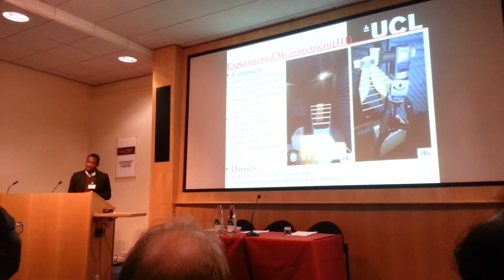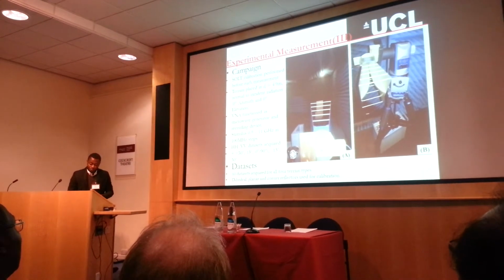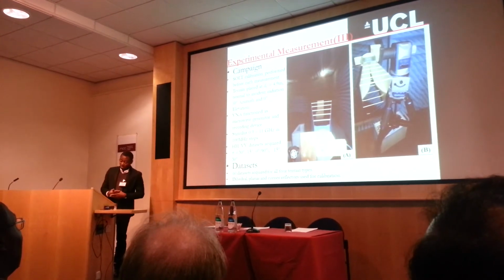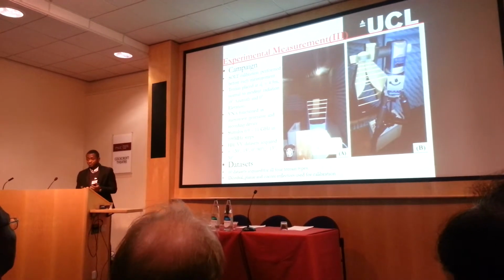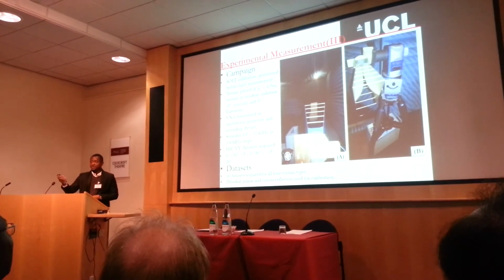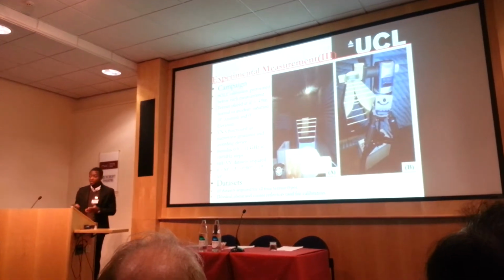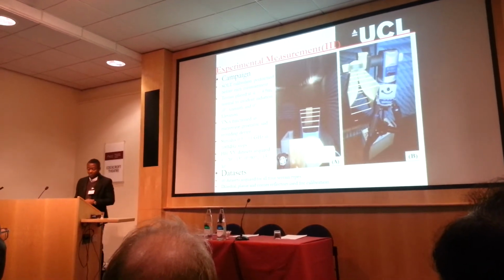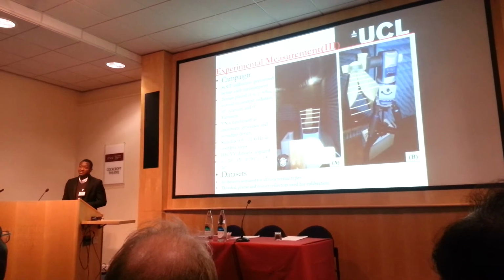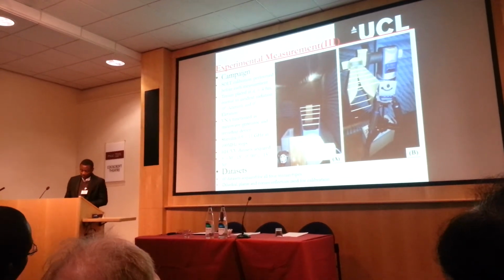The vector network analyzer functioned as both the transmitting and receiving device. We looked at horizontal transmit, horizontal receive, and vertical transmit, vertical receive at these angles: 30 degrees, 15 degrees, nadir, that is straight down, 0 degrees, and 90 degrees. Then we acquired about 60 data sets. In order to calibrate our measurements, we used dihedral, corner, and planar reflectors.